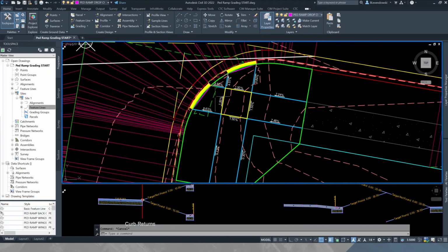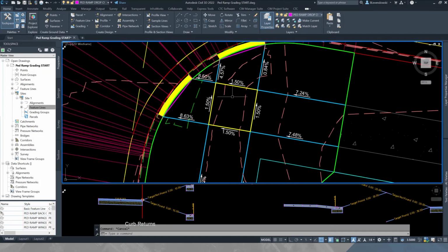So what I recommend is draw out the geometry for multiple ramps at once, and then go into AutoGrader and Quarter Mapper, generate this stuff for you, then do your tweaking after the fact. You might even leave your tweaking kind of towards the end, right? It only takes a few little feature line edits to make that happen.